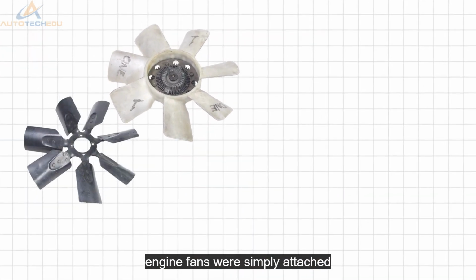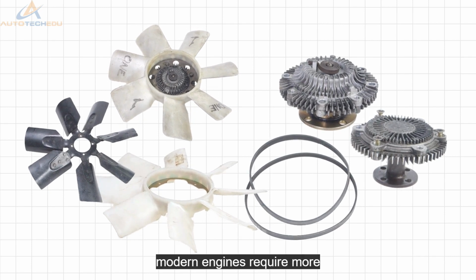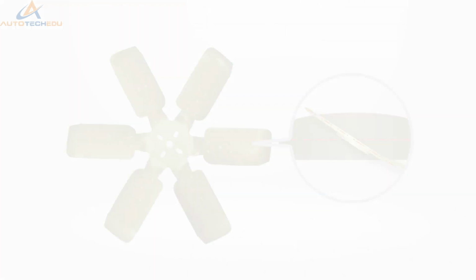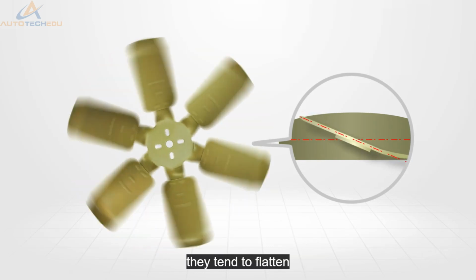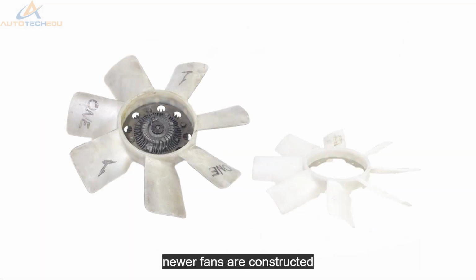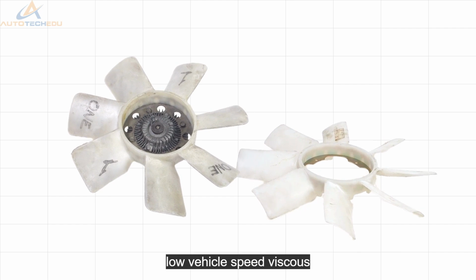Originally, engine fans were simply attached to a pulley and driven by a fan belt. They had fixed blades and were efficient for early engines. Modern engines require more sophisticated systems. These systems may include variable pitch fans, viscous couplings, or electric fans. Variable pitch fan blades change angle at different engine speeds. They tend to flatten out at higher RPMs, as the higher vehicle speed should be sufficient to supply a steady stream of air through the radiator. Newer fans are constructed of plastic and are designed with the blades asymmetrically placed around the circumference. This reduces blade noise at low vehicle speed.